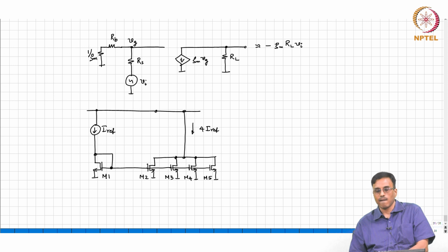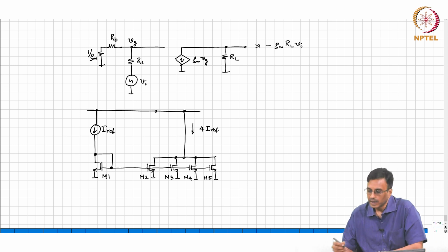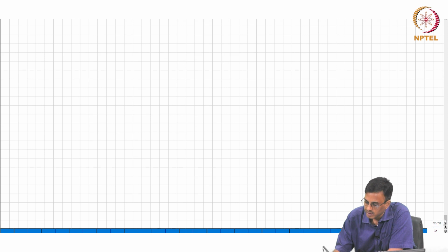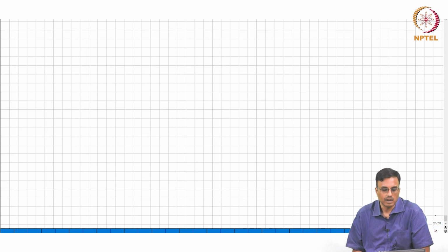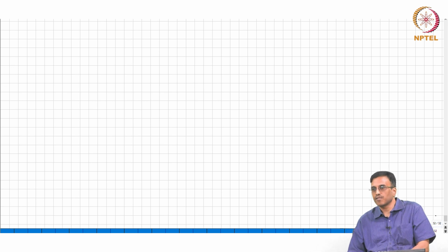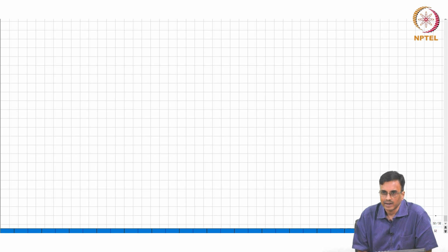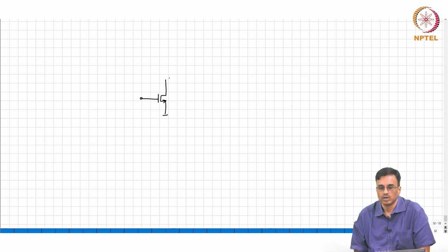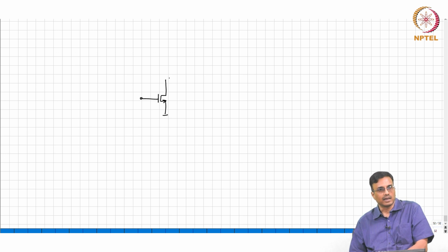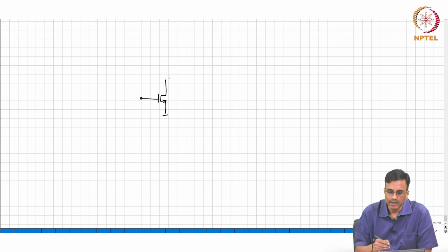All right. Okay. Now, sometimes when people are building discrete circuits, where you do not have this luxury of having multiple identical transistors, let us say you only have one transistor, and you want to make a common source amplifier, but you want to bias it such that the current is equal to Iref in a robust fashion.